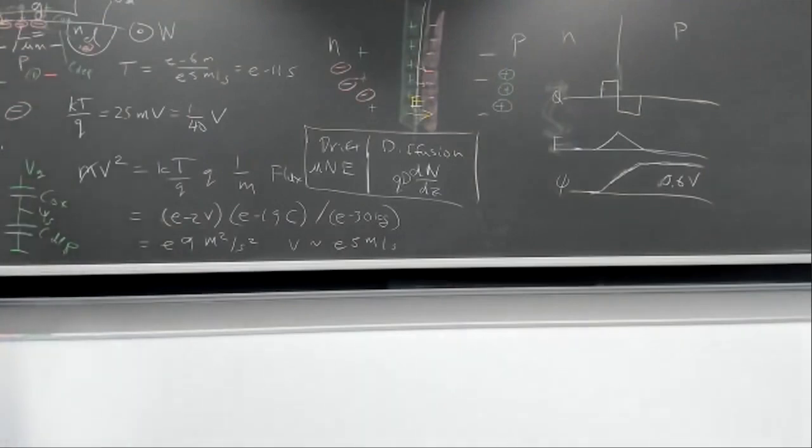But your question was related to this MOS capacitor. Yes, you're right. This is a metal oxide semiconductor capacitor, right? One plate of the capacitor is the gate. The other plate is this depletion layer or this layer of inversion charge, one or the other. But you do need a source and drain there to get the charge from if you're going to invert the surface.